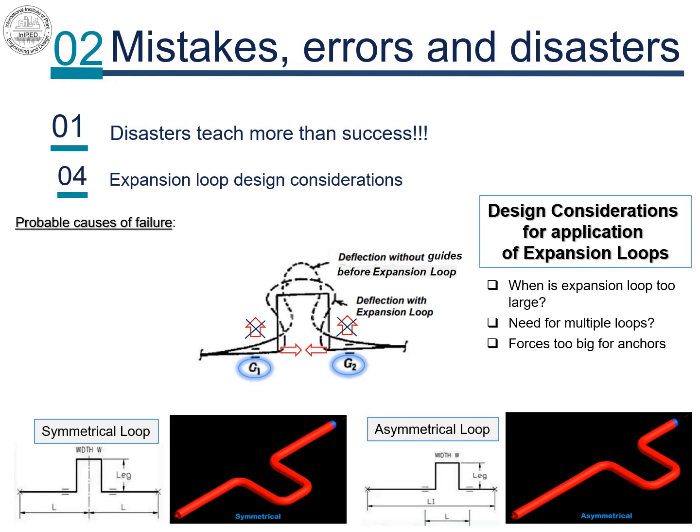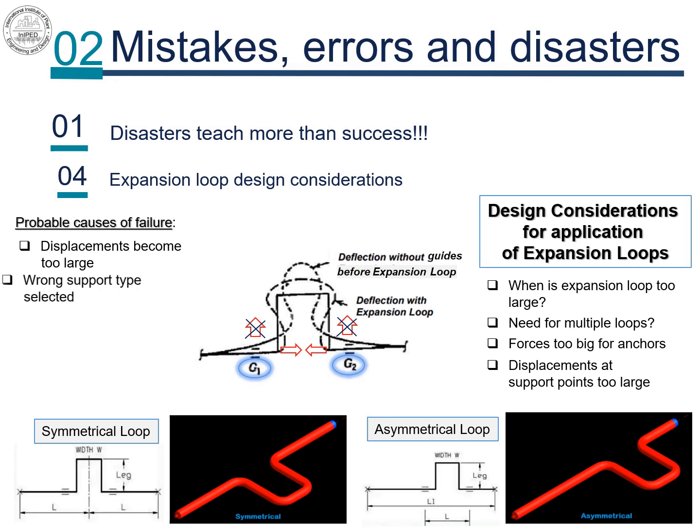More than one loop may be required also when the displacement at support points cannot physically be tolerated by the bearing surface of the support structure. In other words, when bearing surface has been the limiting factor which has to govern failure to meet the mentioned criteria, and considering the particular physical concepts may cause failures. Perhaps, the displacements became too large for the supporting structure to hold up, the support type was not properly selected for guiding purposes, they should have had hold down possibility also, and the forces exceeded the load carrying capacity in lateral direction. Therefore, the line has collapsed by slipping laterally.